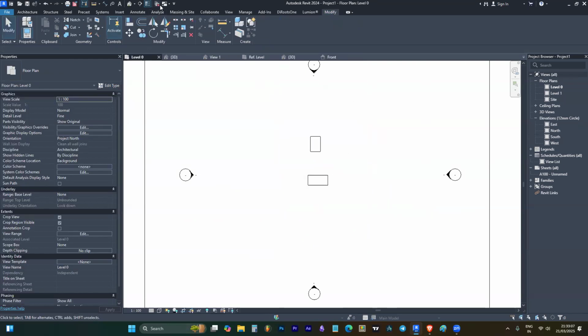Now I'm trying it. See, our previously edited values are 6000 and 4000. Now it was taking the values from the project, 1000 and 1500, and implementing them back to the project. So now it was affecting the previously edited family here, right? So that is the dialog box we have seen while importing the family again.